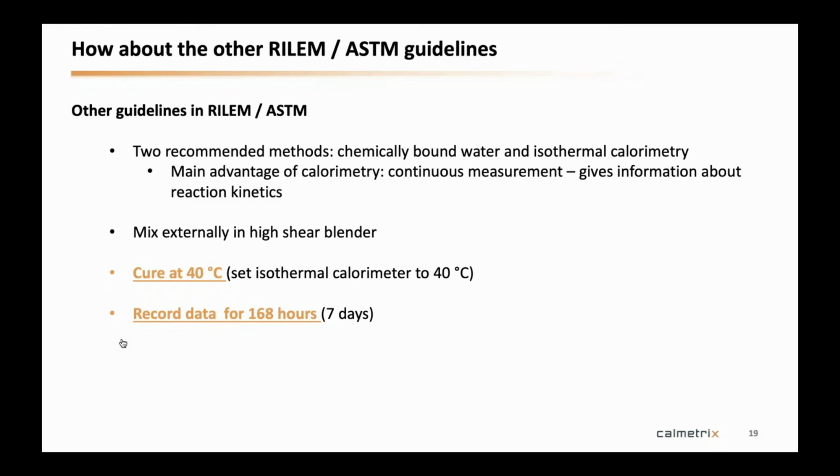So it's definitely doable. There's no question that it can be done. And now that we have a system to mix internally and mix efficiently, now that it exists, let's just use it and see if we can capture the early reaction. And let's just test the whole thing. And as we do that, let's look at the other recommended guidelines that we have in RILEM and ASTM, in the upcoming ASTM. So we say curing at 40 degrees C and record data for 168 hours. Okay, so we did that.